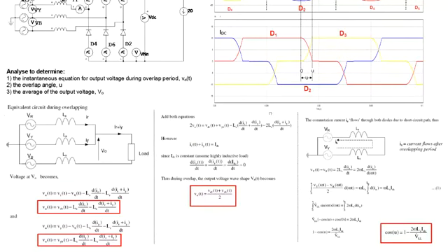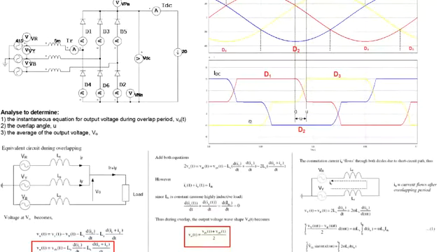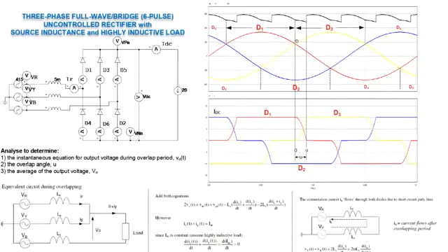This is actually the average. The voltage here, Vout, is actually the average between the two line-to-line voltages. There's a line-to-line voltage across that and across that. And if we look closely, the Vout during this overlapping period is actually in the middle between the two line-to-line voltages.